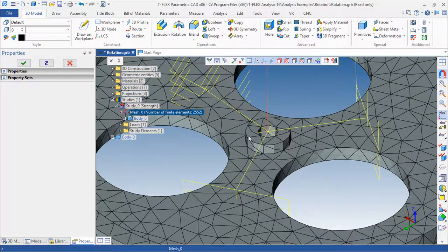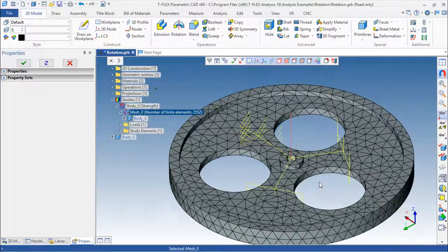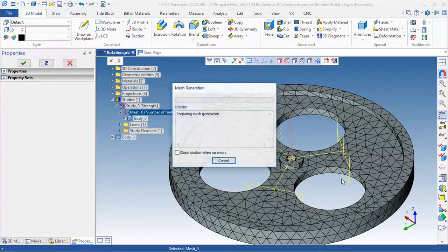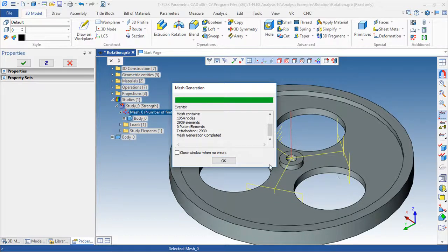Even so, in this detail here, because it is a very small detail, I'm still not very happy with this part. So I should increase the definition a little, and I can do this on the curvature, saying that the mesh size in the other places is good, but in this curvature area I would say, for example, 0.2, and okay, let us create a mesh and see.